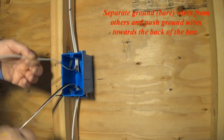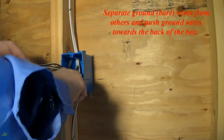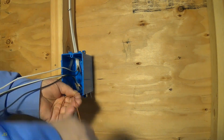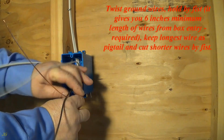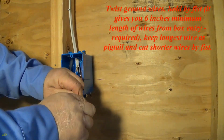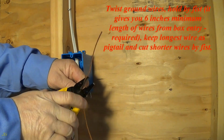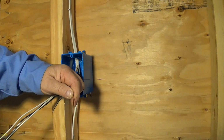Separate ground, bare, wires from others and push ground wires towards the back of the box. Twist ground wires, hold by fist, it gives you 6 inches minimum length of wires from box entry, required. Keep longest wire as pigtail and cut shorter wires by fist.